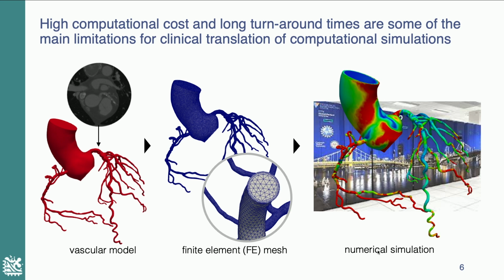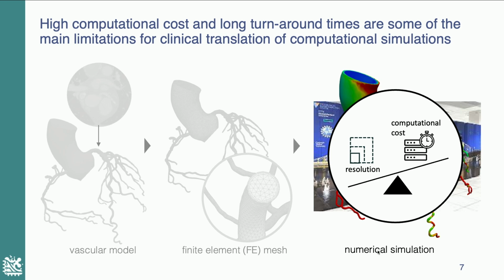These may take anywhere from hours to days, depending on the resources you have available. But this is not something practical for clinical applications. Now, there's always going to be a trade-off between how much resolution you can get in your simulation. If you need to fully resolve all the flow details, for example, all the flow near the wall to get a good wall shear stress approximation, that computational cost is going to go up.